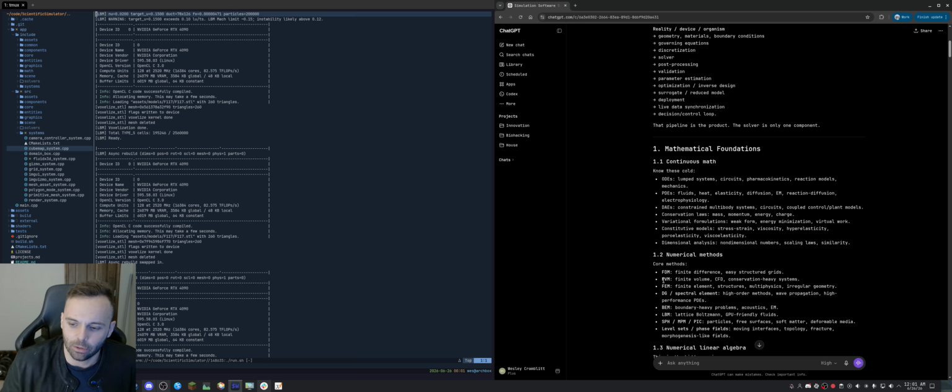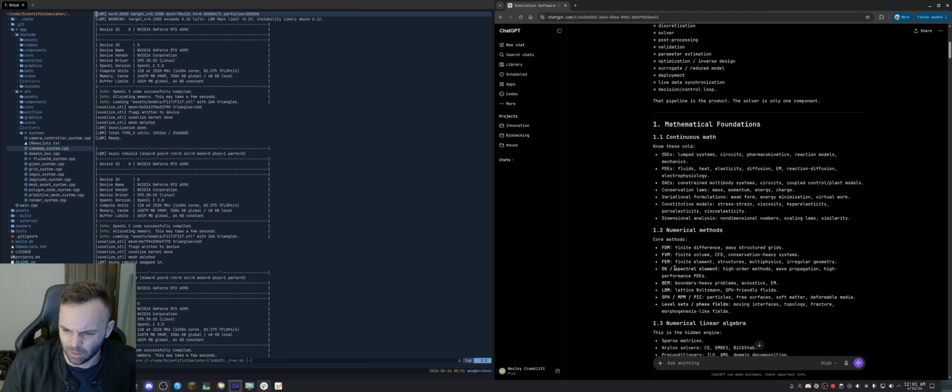And from my current knowledge, finite volume is one of the best, but it's very difficult. It's very rigorous math, and finite difference is pretty easy, but it's not very accurate at all, and it's also kind of slow. I think spectral is used a lot for hypersonics. Lattice Boltzmann, yep, GPU friendly. I was just about to say that. Because it's a grid, so it's really easy to represent on a GPU, since GPUs just solve the same linear algebra multiplications and stuff many times at once.